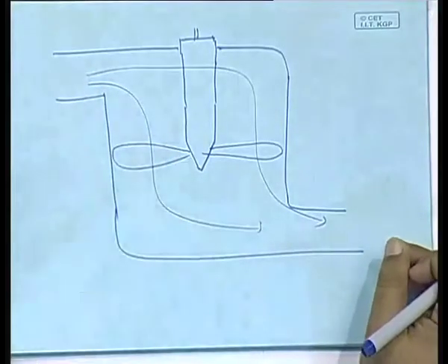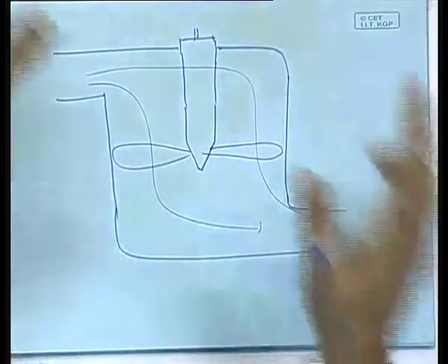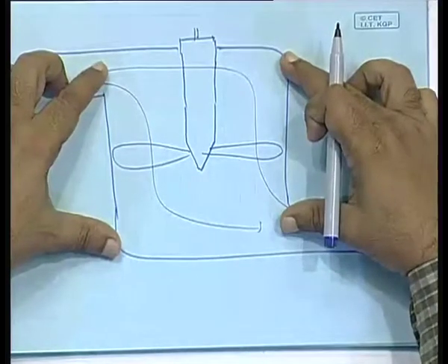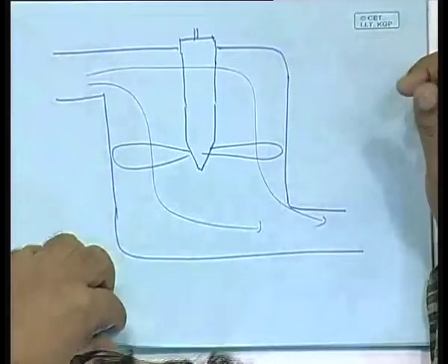And in very low head power plants, which are placed almost in plain lands, the amount of head available is only a meter or two. In those cases obviously you cannot have even this much height difference between the two sides. In those cases you have, as we called, the bulb or tube turbines.